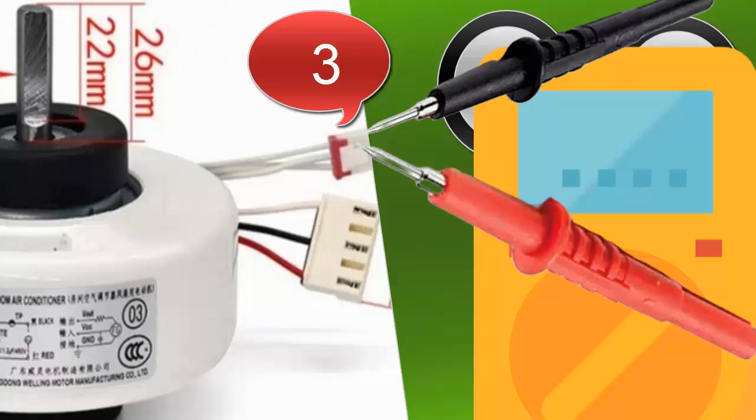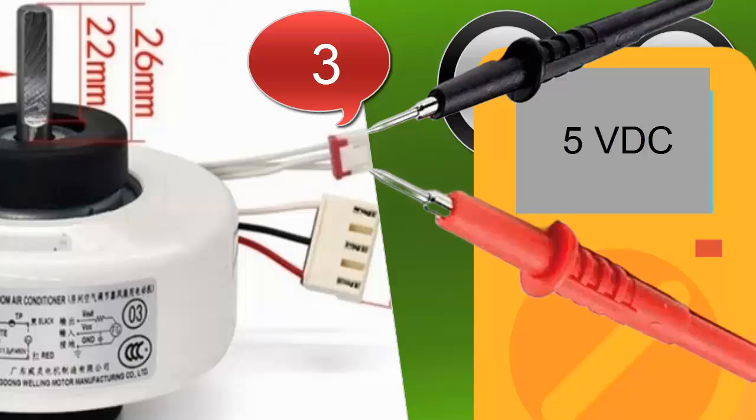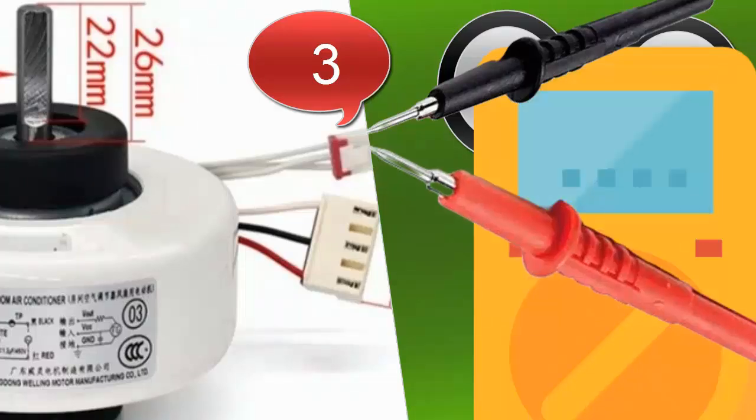To identify the power supply and ground wires, power up the electronic board, and use a multimeter in the DC voltage range to find the pins that show a constant 5V value. The pin or wire in contact with the red lead of the multimeter, when the reading shows 5 volts, will be the power supply, while the pin in contact with the black lead will correspond to the sensor's ground. The remaining third pin will be the sensor's output signal.